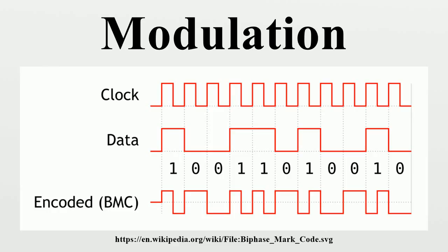Fundamental digital modulation methods. The most fundamental digital modulation techniques are based on keying. PSK: a finite number of phases are used. FSK: a finite number of frequencies are used. ASK: a finite number of amplitudes are used. QAM: a finite number of at least 2 phases and at least 2 amplitudes are used.